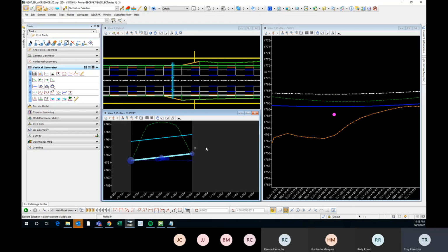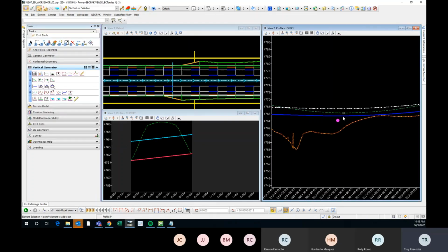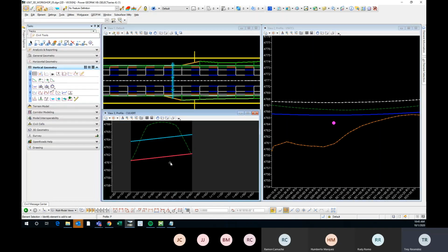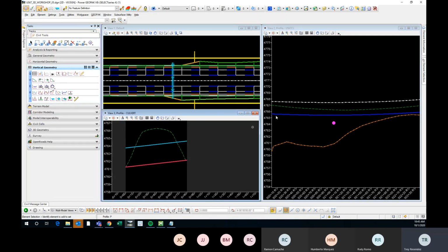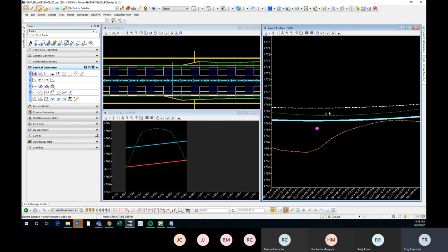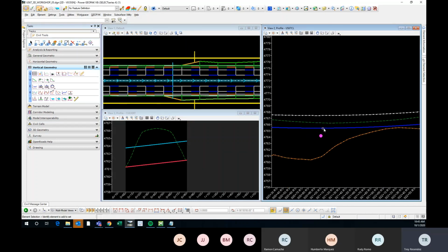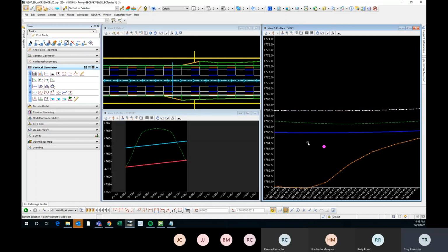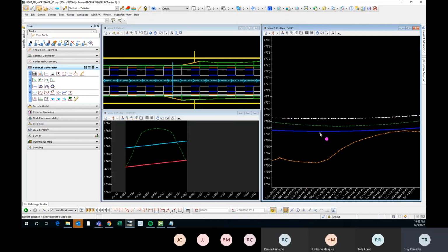You really just pick the offset that you choose. It would be the structure depth, either the structure depth only on your PGL, or the structure depth plus the cover that you want. And then you either do that or you add the cover to your culvert here, your depth of cover. So let's just be aware of that.